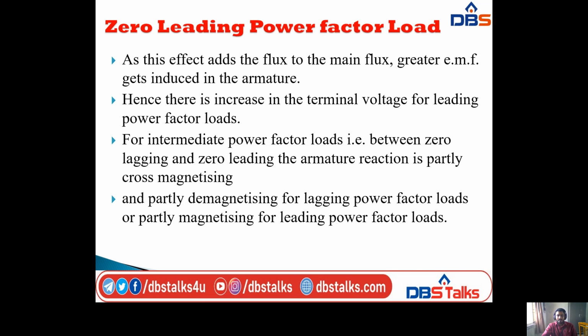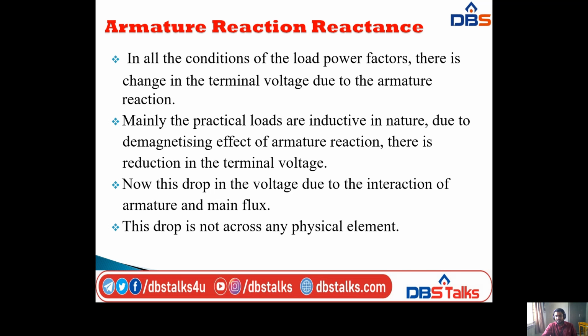And next, armature reaction reactance, that is XAR. In all the conditions of the load power factors, that is unity power factor, zero lagging power factor and zero leading power factor, there is a change in the terminal voltage due to armature reaction. Mainly the practical loads are inductive in nature. Due to the demagnetizing effect of armature reaction, there is a reduction in terminal voltage.